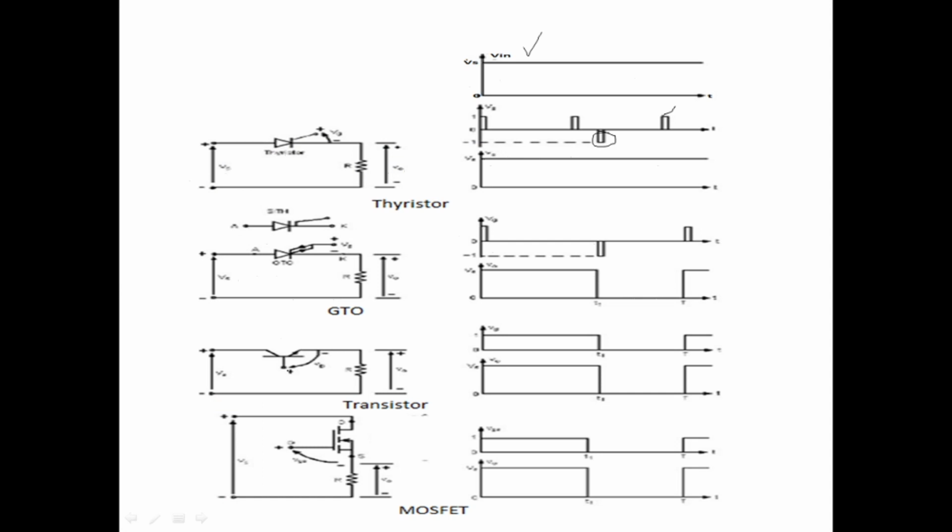If the base emitter is not forward biased, the transistor cannot enter into the on state. We have studied that IB, the base current, is the control variable. In the sense, if IB is 0, the current IC is also 0. You have studied very well, IC is equal to beta into IB. IB itself is 0, so there is no chance of IC.